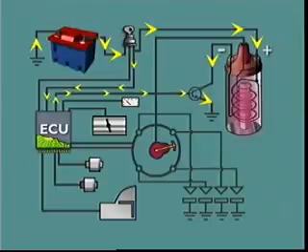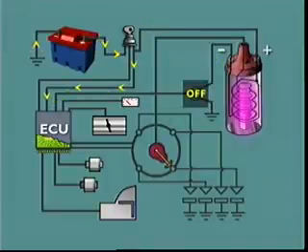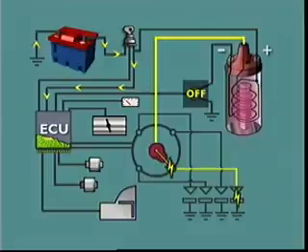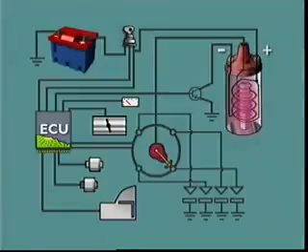complete the primary circuit. Once the appropriate dwell period has elapsed, the module switches off the voltage applied to the base of the transistor, and the transistor switches off the primary circuit. The high-tension secondary voltage is then transmitted to the center of the rotor arm and to the appropriate cylinder. This cycle is repeated for each cylinder in turn.